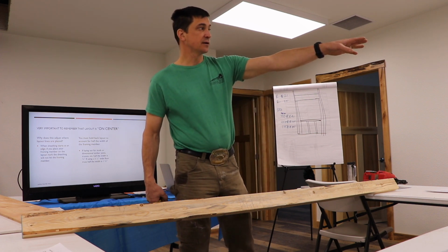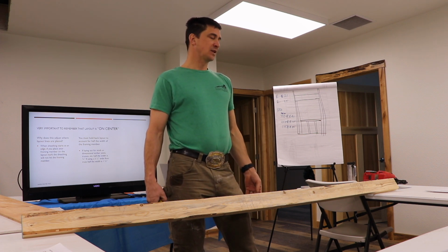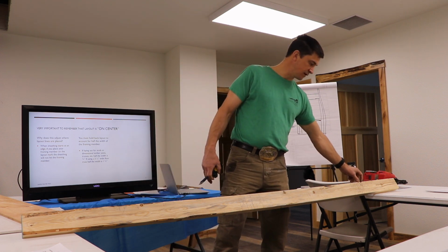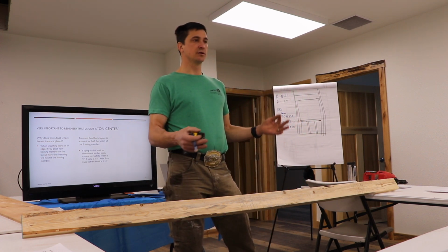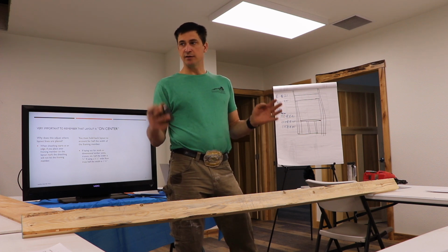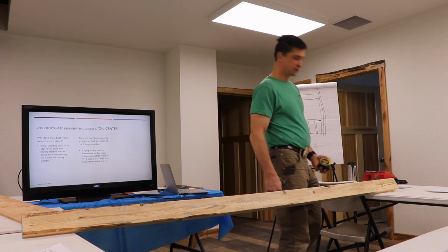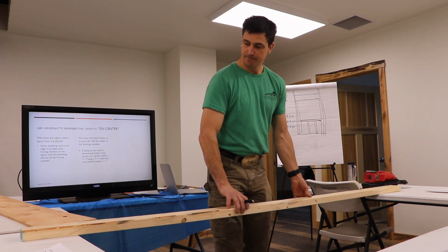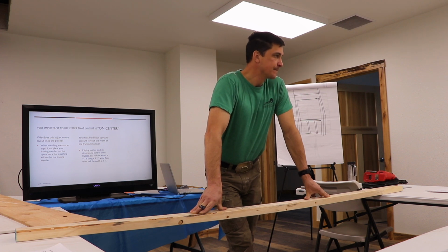like any of those windows there, if it's centered over the kitchen sink, you probably want to keep it centered, even if you have a stud on layout 7/8 of an inch away, just because they may have cabinets already ordered, and the cabinets are done off the plan layout and that kind of thing. But if it's in a bedroom, I'll move it over. So let's say that you have the window that specifically has to be where it needs to be, you can't move it over. And then that one stud, that's 7/8 of an inch away, that's where your drywall seam is.